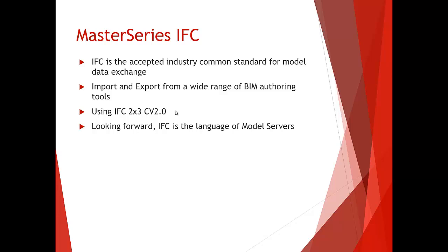Can we do a round trip type of integration? Well, the answer is not today. Basically, how all of that type of change is managed is something called model servers, BIM model servers, and IFC is certainly the language that's used for BIM model servers. They're very much still in an embryonic stage in terms of take up, but the implementation of the IFC places us well to be a part of that change moving forward.